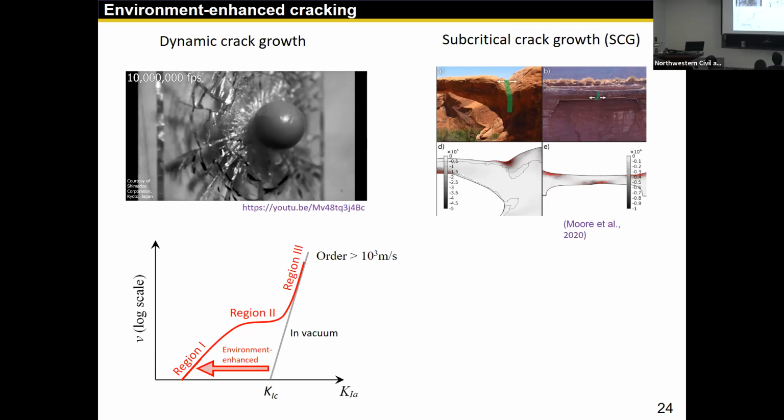They identified cracks along these arches. Then they ran a three-dimensional finite element model to identify the stress distribution in the arches and found the regions where some tensile stress shows up, corresponding to where they can find a crack. Of course, there are many other reasons that can cause a crack, but since these are very strong correlations, they suspect this was caused by subcritical crack propagation.